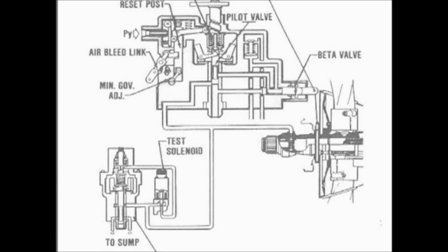But here we're at the overspeed governor, which is right here. We have the solenoid to the overspeed governor. This switch is actually in the cockpit on the left hand side. We have the primary governor, we have the propeller, we have the engine shaft. Okay, so the overspeed governor is set at 104% MP, which converts to 1976 RPM. The governor in its overspeed condition will think that it's at 1976 RPM.